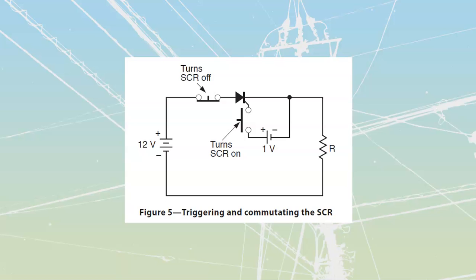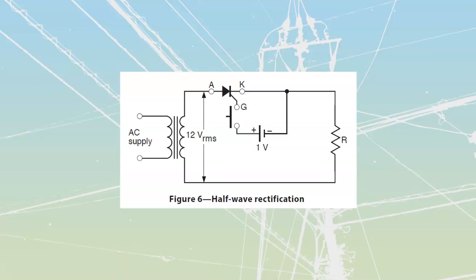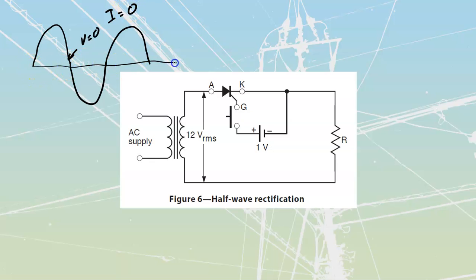If I placed it into an AC circuit, we all of a sudden have this wonderful thing where we are going to be able to shut off the current automatically because our AC current does that. AC starts, builds up, hits 0, builds up in the opposite direction, hits 0, builds up in the opposite direction. Anytime that my voltage is equal to 0, therefore also my current would have to be equal to 0 no matter what the value of resistance is, which means that guaranteed anytime that I cross this line, that's something called commutating. You should remember that from your AC theory at the beginning of second year. Anytime that I go into commutation, I'm going to drop below holding current and it will automatically shut itself off.